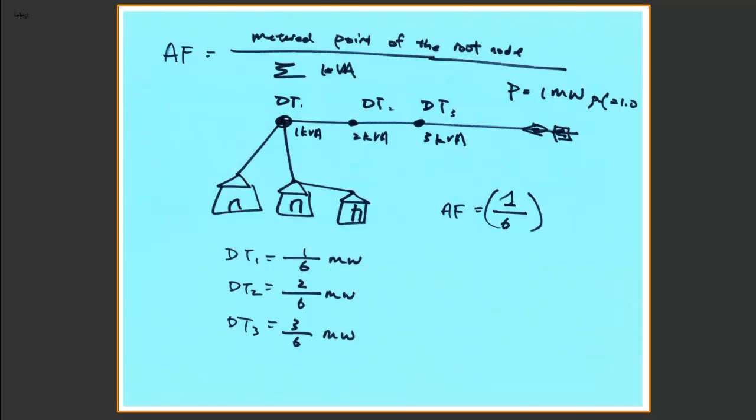So I have been talking a lot about location factors, partly because as part of the distribution system, there is a limited number of metering points across the feeder, from the primary side of the network to the distribution side of the network. So since we need an initial value for the power flow P and Q, we used this to allocate to the child node, which is the load that doesn't have a metering point, from the root node of the subsystem. And the definition of location factor is the ratio of the meter point of the root node, which could be the substation feeder head or any part of the distribution feeder, primary to distribution, as long as it's a meter.